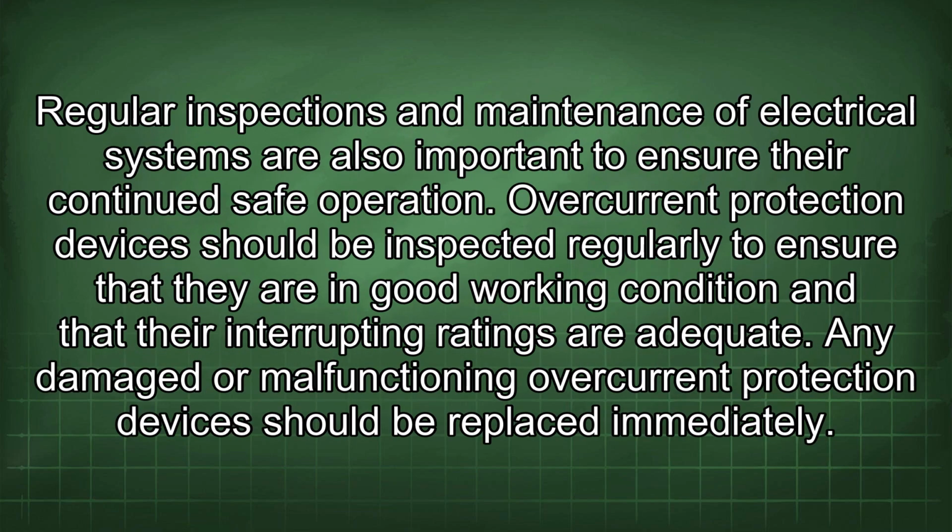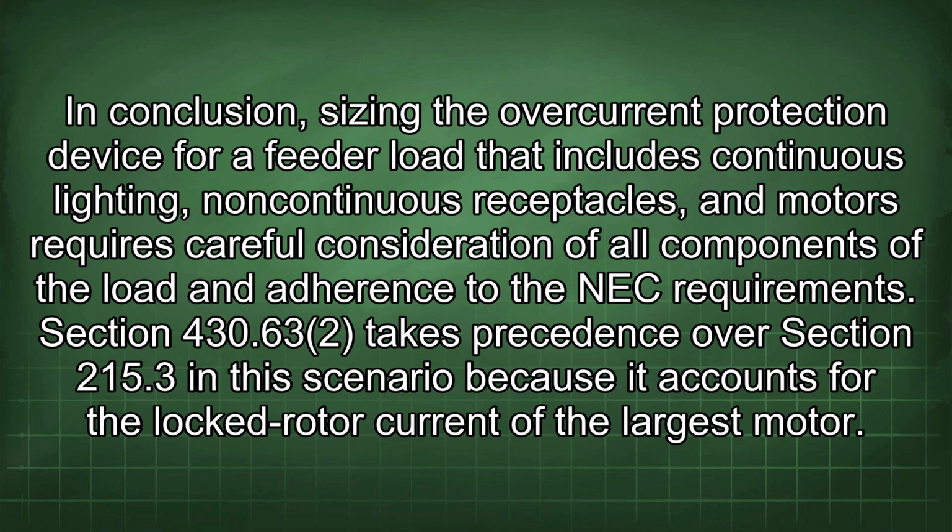Regular inspections and maintenance of electrical systems are also important to ensure their continued safe operation. Overcurrent protection devices should be inspected regularly to ensure that they are in good working condition and that the interrupting ratings are adequate. Any damaged or malfunctioning overcurrent protection devices should be replaced immediately. In conclusion, sizing the overcurrent protection device for a feeder load that includes continuous lighting, non-continuous receptacles, and motors requires careful consideration of all components of the load and adherence to the NEC requirements.